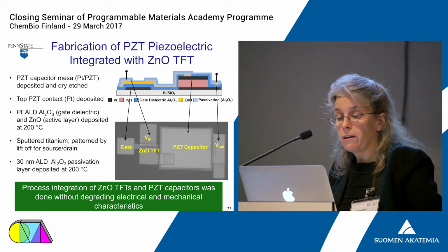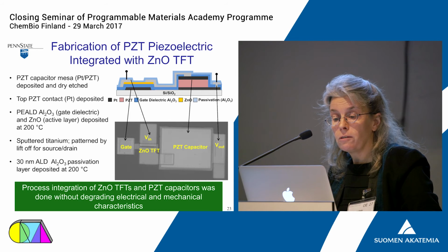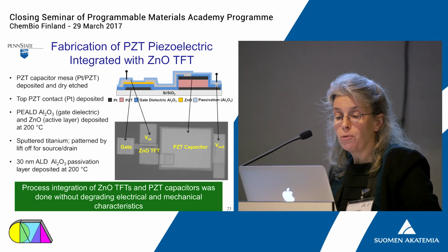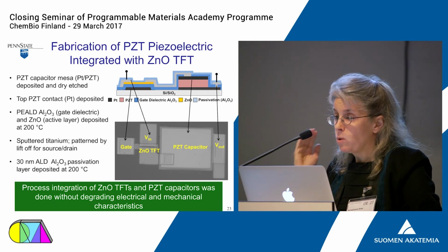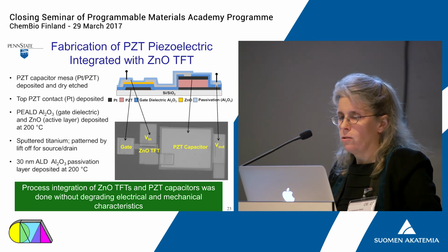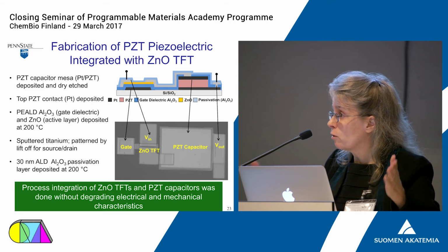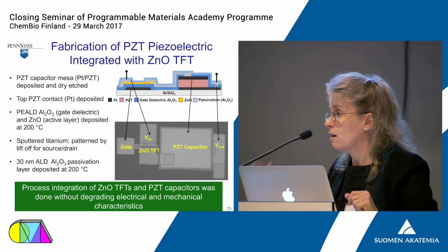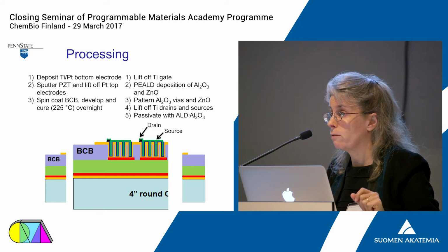And working with Professor Tom Jackson and the Electrical Engineering Department at Penn State, we were able to deposit zinc oxide thin film transistors. These are deposited by a plasma-enhanced atomic layer deposition approach to put down both the gate dielectric and the functional semiconductor, the zinc oxide. And then we aimed every technique that we knew how to use to figure out whether the zinc oxide affected the piezoelectric or the piezoelectric affected the zinc oxide. And the 2 processes appear to be totally separate, one from another.